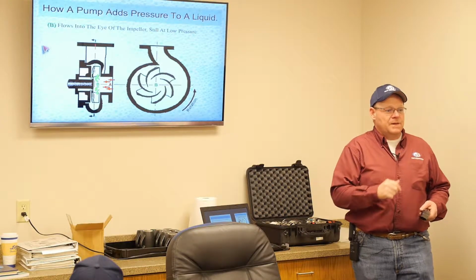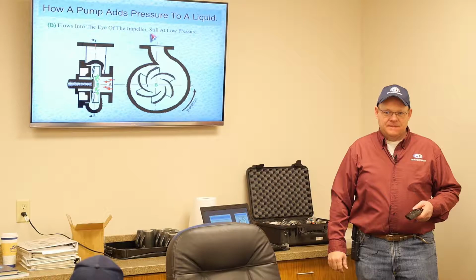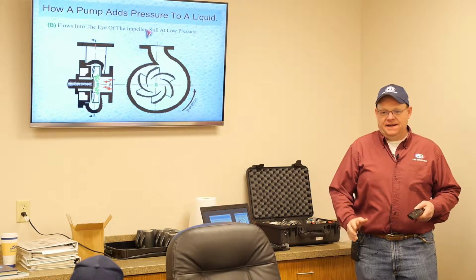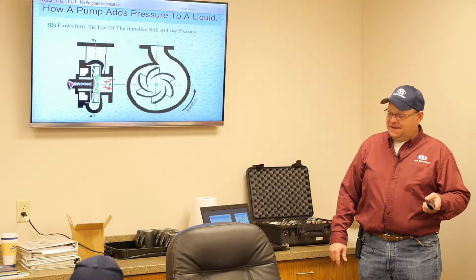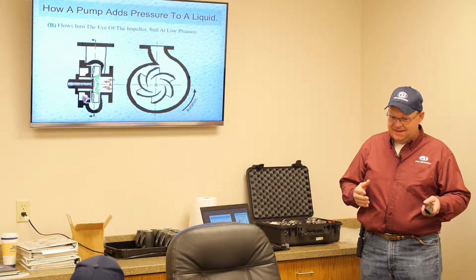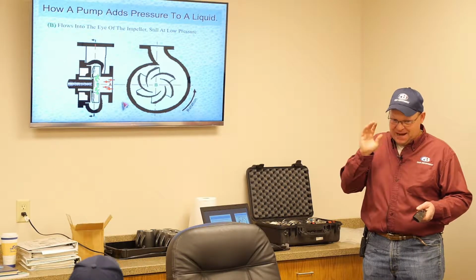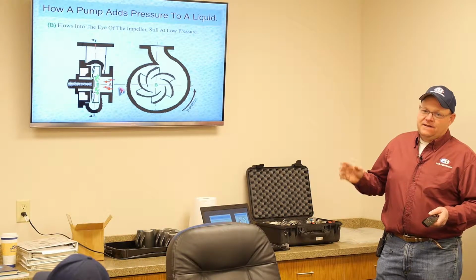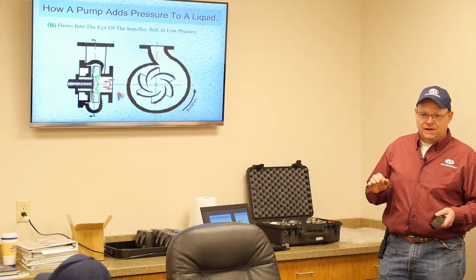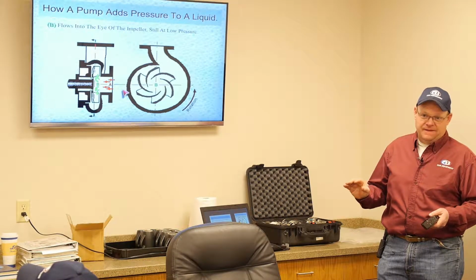Will a centrifugal pump run backwards? Yeah, probably. To a degree. Don't run the Gould's version backwards, or even the Durco. Bad things happen, and we'll go into that when we get to the hands-on stuff. But it will pump backwards. It's usually about 1/3 to 25% of the normal flow and nearly zero pressure.